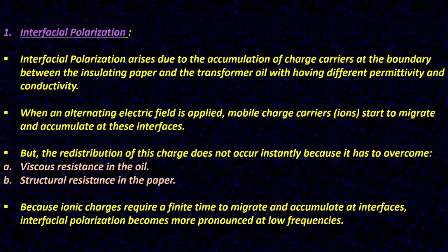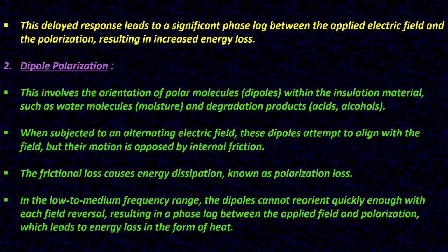Because ionic charges require a finite time to migrate and accumulate at interfaces, interfacial polarization becomes more pronounced at low frequencies. Most important, the delayed response leads to a significant phase lag between the applied electric field and the polarization, resulting in increased energy loss.